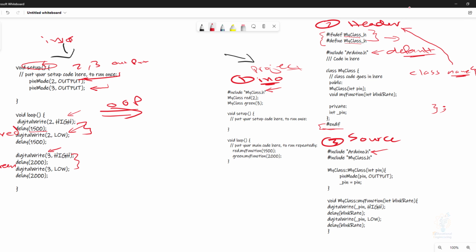Now, in Arduino libraries or in C libraries, we usually create prototypes right away, but here we will create them inside the class. The first step is adding two words, public and private. Now, public with two dots and private with two dots. The public here will include the public functions that we can call inside this project file.